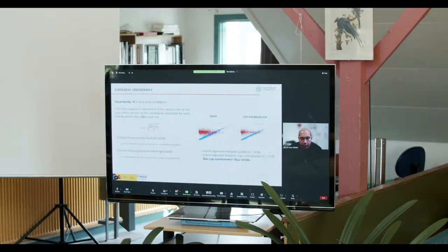We have finally obtained the statistical uncertainty using the K-fold cross-validation. That is the method that is set out in the standard. And finally, we see that, taking into account the LIDAR, it's better to use the equivalent rotor wind speed. And well, we see that the type A uncertainty, well, it's in Spanish, but this is the type A uncertainty for the site calibration is more or less 0.006, and in the other case, using only one measure, it is 0.001.